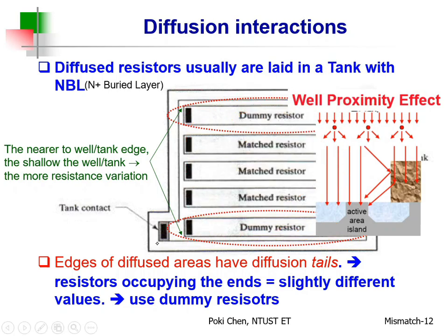Well proximity effect. Why? If you are at the boundary, you will get more doping or diffusion simply because, according to the 3-dimensional structure, this is some kind of cross-sectional view. Alright? Don't expect the impurities, never mind through doping or implantation, will always go in this direction. Sorry for that. I warn you again and again already. Right?